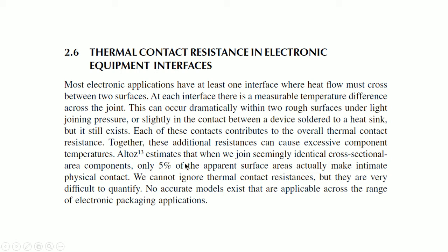5% of the apparent surface actually makes intimate physical contact. You have seen that, no? In the very early beginning of the lecture I told you, even the so called metal to metal, that is, if you take, let us say, 10 mm by 20 mm copper rod, and then try to attach it to another 10 mm by 20 mm copper rod, and try to conduct heat.